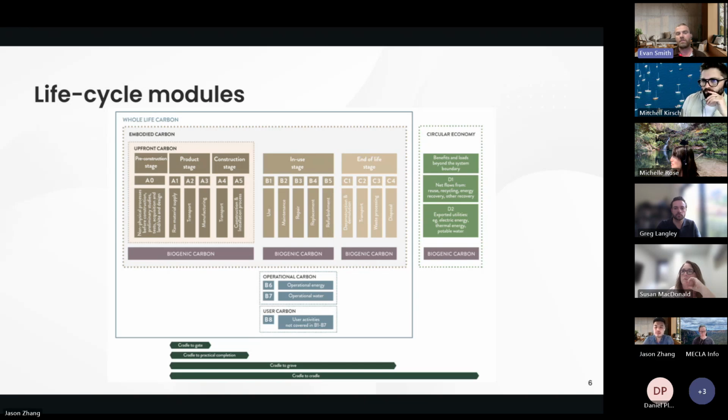But typically, for a customer, when someone uses it for, say, a Green Star or infrastructure project, they take the A1 to A3. That's from the gate at our concrete plant, and then they'll model their own transport to the site, their own installation of what they actually did, and then they might use our end of life scenario if they want to run a scenario.